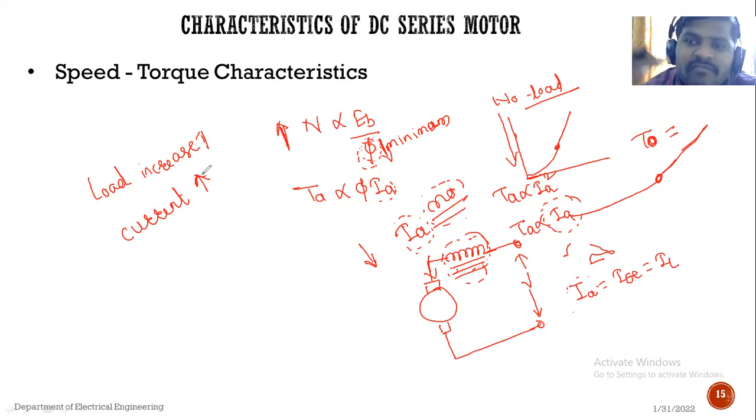Now what is the meaning of without load, what about torque? Do not start without load, that means at what torque should we start, maximum or minimum? Maximum. That means somewhat of a load can be put on the machine. So some torque will be present before starting the machine, and we will start the machine when near about 25% load can be put on the machine. Then the machine will start safely.